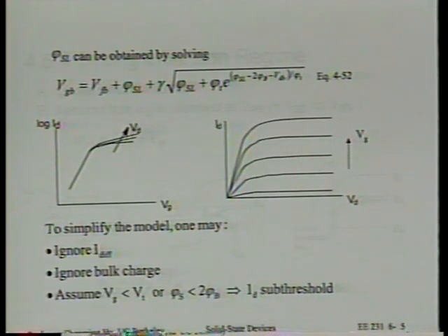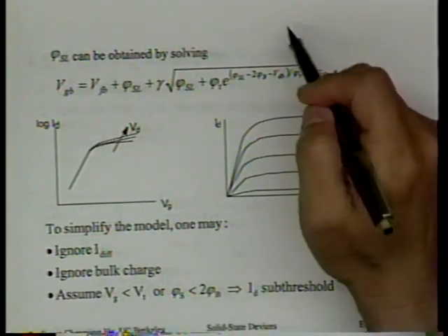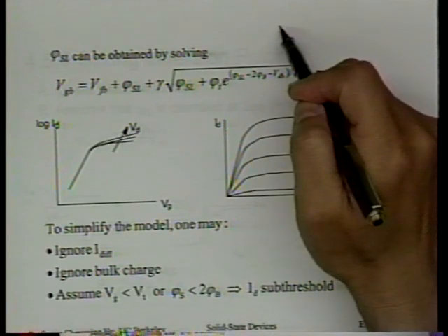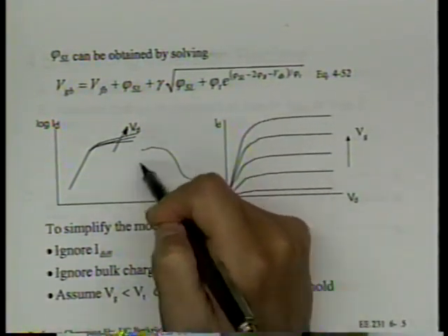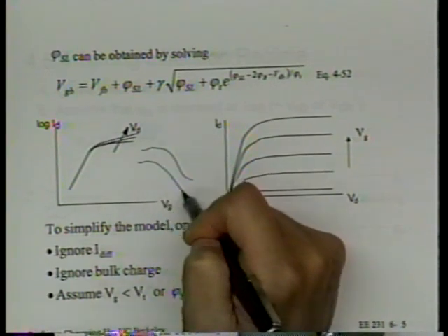Yes, question? What about the Fermi level all along the channel? No problem. You can use that concept as well. The problem is, however, we don't know the quasi-Fermi level in the middle between the source and drain. Last time we already made this point that if we really insist on drawing the quasi-Fermi level all the way from source to drain, we can.